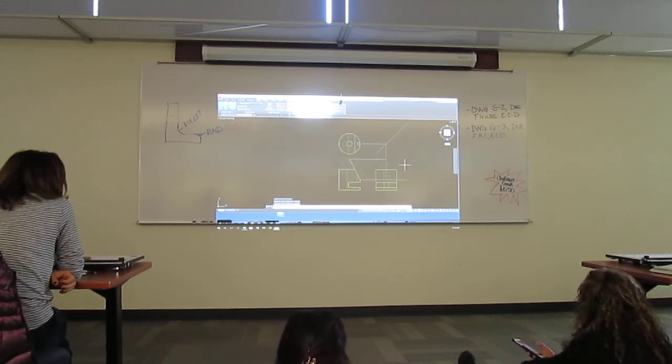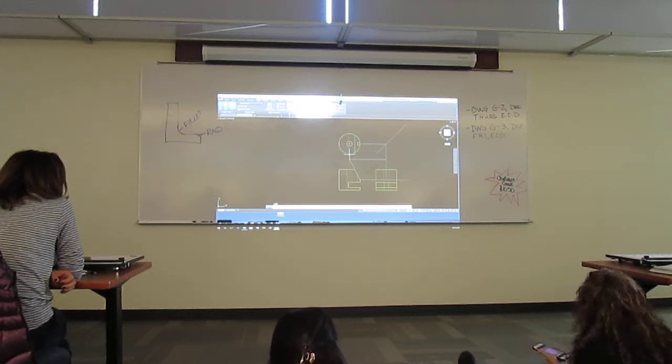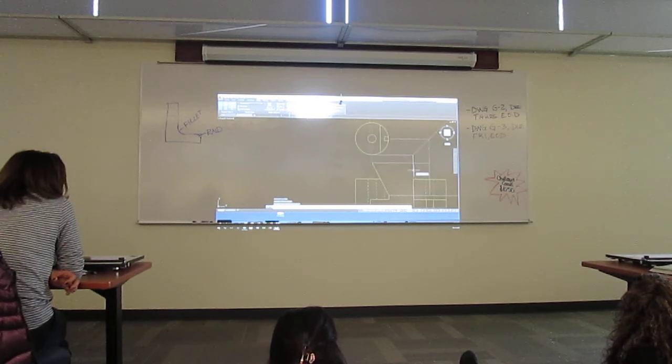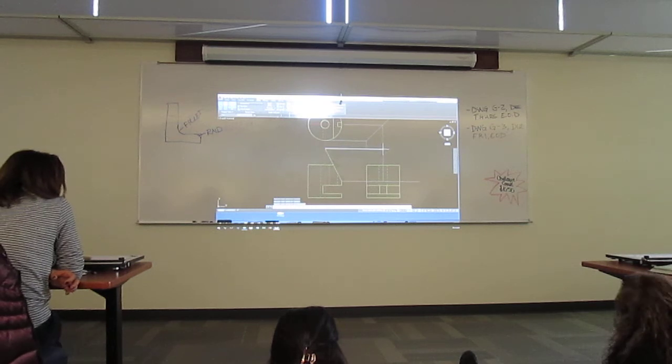Where is my minor radius of my ellipse? It is this piece right here, right? Because I've projected it up to the center line. Oh, got a bad snap there. So it's going to go from here to here to here. So what I've now defined, there's the center of my ellipse. This is my minor radius. This is my major. Let me draw the ellipse now.